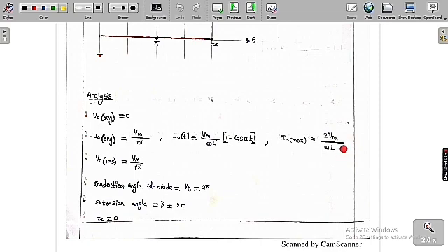And I have already told you there is no extra branch, therefore the output current is always equal to the source current. So their average values are equal, and RMS values are also always equal. The RMS value of the output voltage is equal to Vm by root 2. The conduction angle of the diode, gamma d, means the diode is always conducting from 0 to 2 pi, so its conduction period is 2 pi.